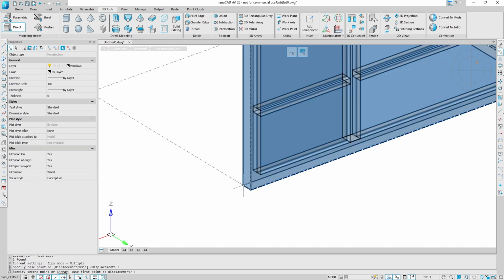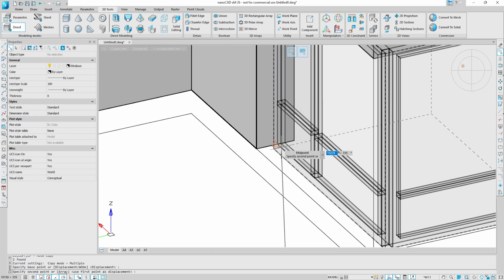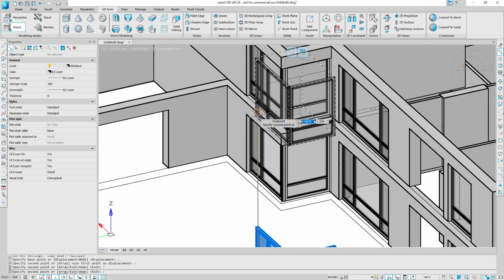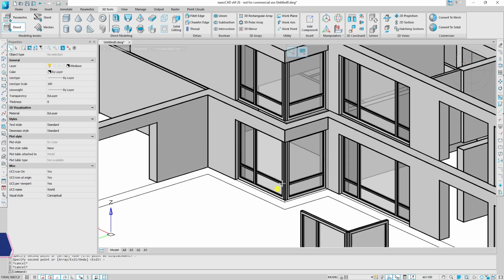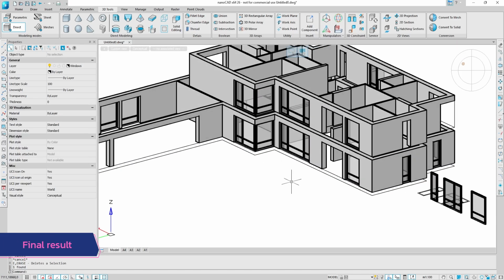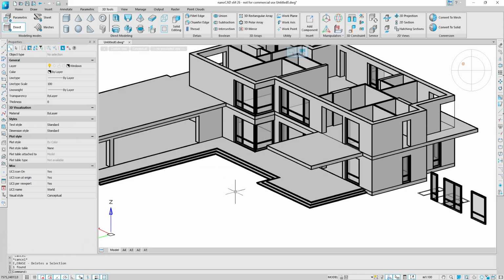The second corner window can also be placed on the ground floor, or you can leave this opening under the door, as it was designed. In total, we have placed 20 windows in the project, 13 windows on the ground floor and 7 on the second floor. Leave the remaining 10 openings for the doors, which we will create in the next lesson.